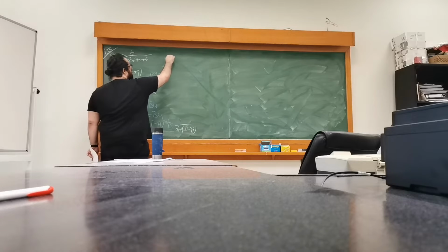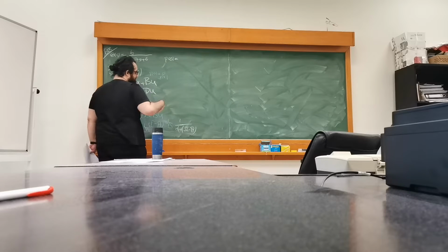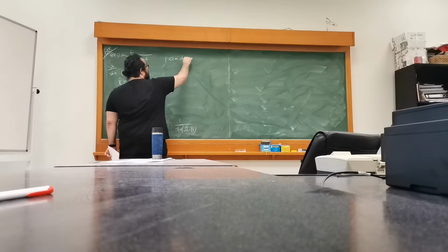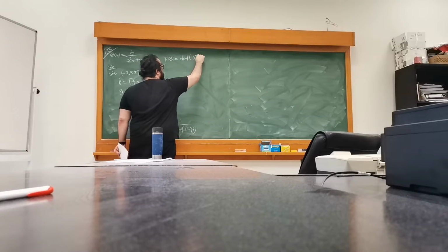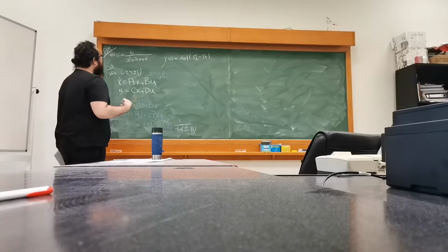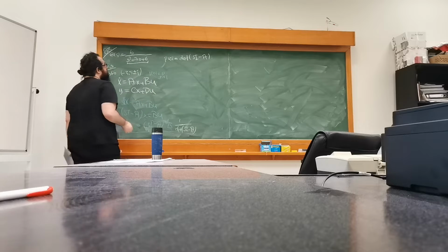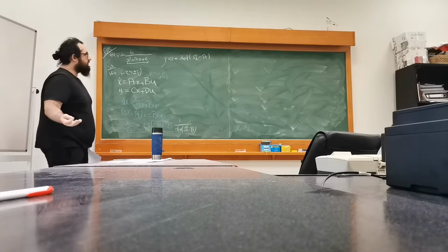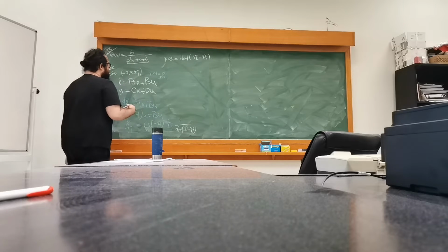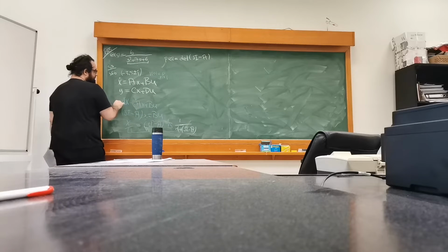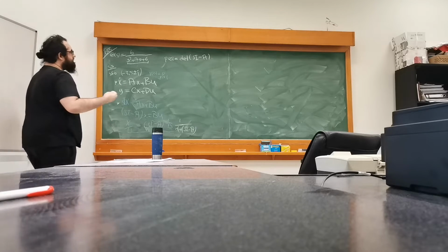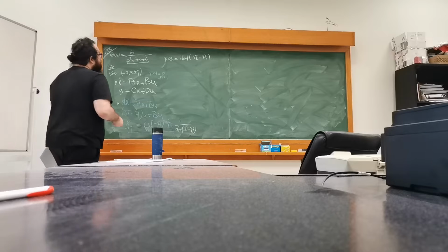If I want to look for P(s), as I'm used to in classical control, I can use the determinant of sI minus A. Therefore, I will start with only this characteristic polynomial, or the denominator of the actual transfer function, in order to come up with the A and B matrices. So the denominator here is for this equation. A and B will determine this. So let's start with that.